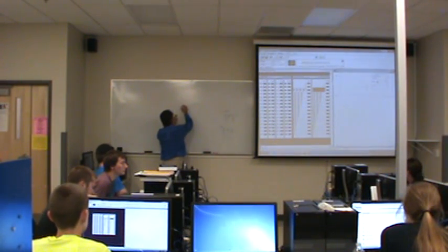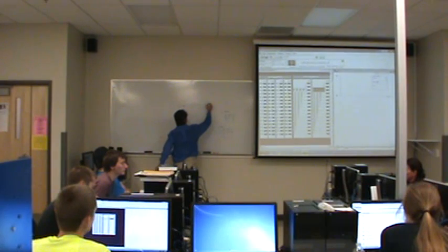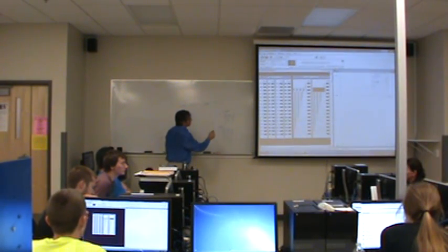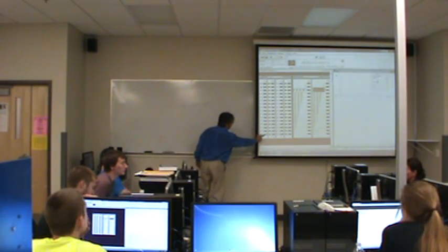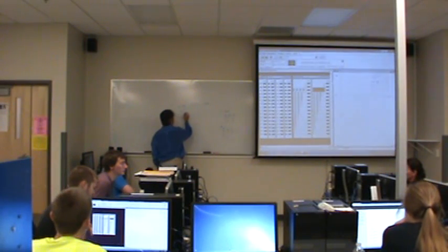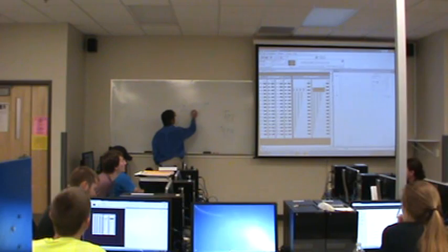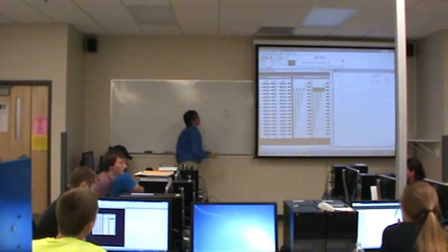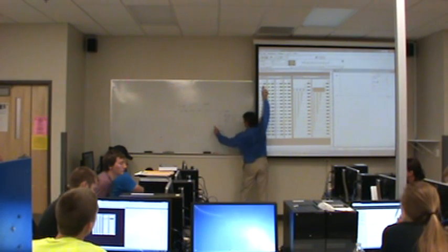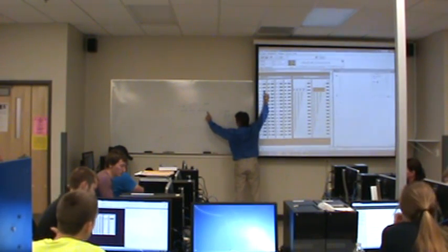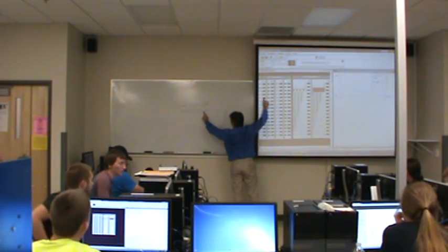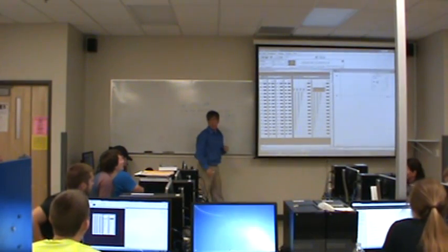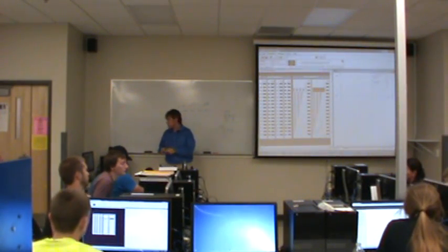It's most significant bit always to least significant bit. And so it would be ignoring all odds, so a 0 for the 15th bit, a 1 for 14, 0, 1, 0, 1, 0, 1, 0, 1, 0, 1, 0, 1, 0, 1. So I'm not going to ignore the 0. I'm not going to ignore the 2. I'm not going to ignore the 4, but everything in between I'm ignoring. Does that make sense? So that's the mask that I want to get.